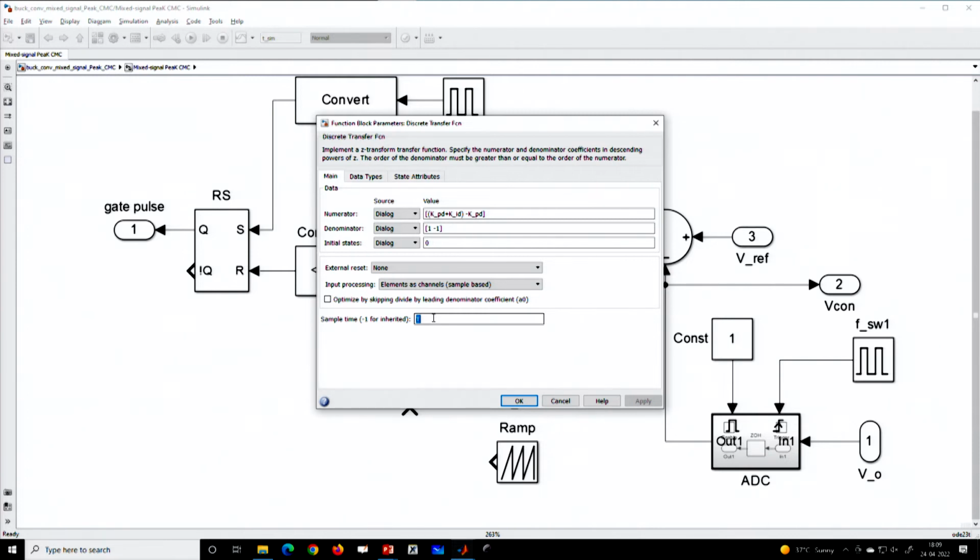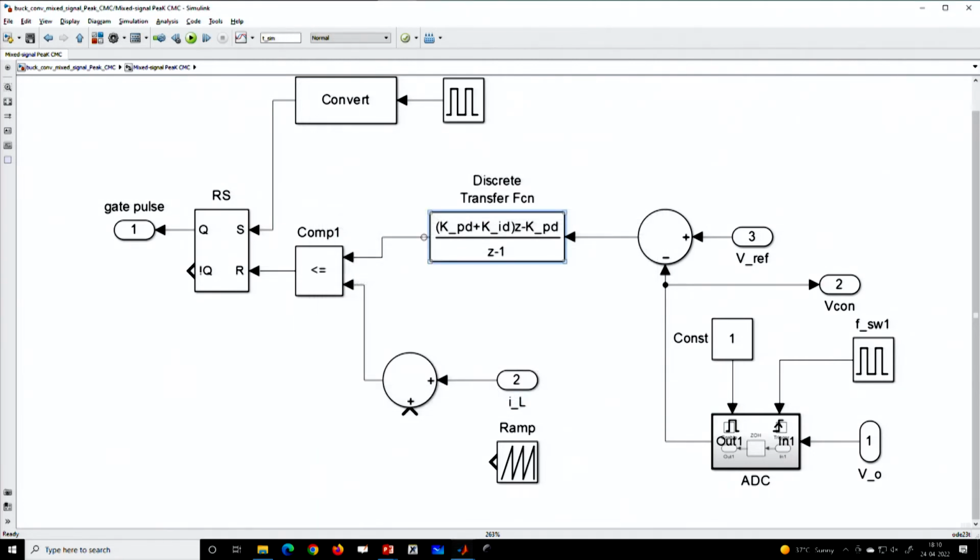But we do not want that. We want the computation to happen once the data of the ADC is ready. Since the ADC clock is shifted, naturally the conversion time will be there and your data will be ready after some time, so you need to start computing after that. So, this transfer function will not allow us to customize the point where computation starts, and this cannot be done by just plugging in this transfer function.